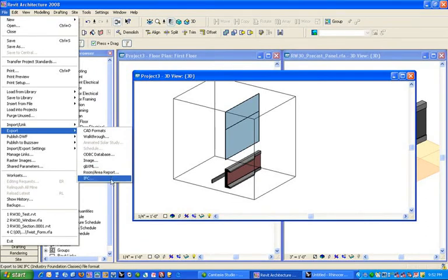And then IFC, which is Industry Foundation Class, it's what the GSA requires in their BIM mandate. So when you're doing work for the GSA, you have to submit an IFC file that they run through a software to check if their areas are correct, because they have area requirements on where you're taking your areas from and how big an office can be and different things like that. And it's an open source format that's used for exchanging BIM files.